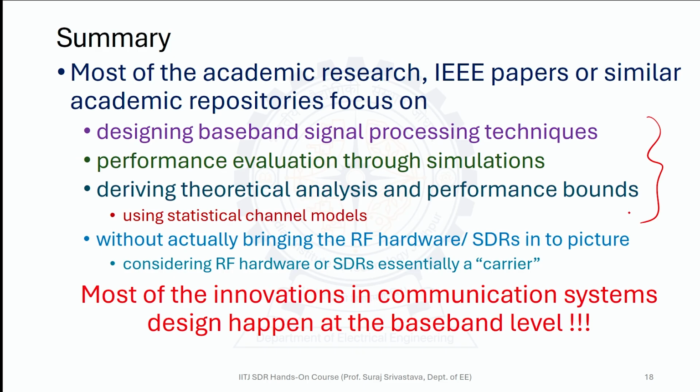You can work on all these things in the simulated environment. So these three things, designing baseband signal processing techniques, performance evaluation through simulations, and deriving the theoretical analysis and performance bounds using the statistical channel model, can be performed without bringing the RF hardware or software defined radios into the picture. The assumption here is that we assume the RF hardware or SDRs to be ideal, and we consider them only as a carrier.